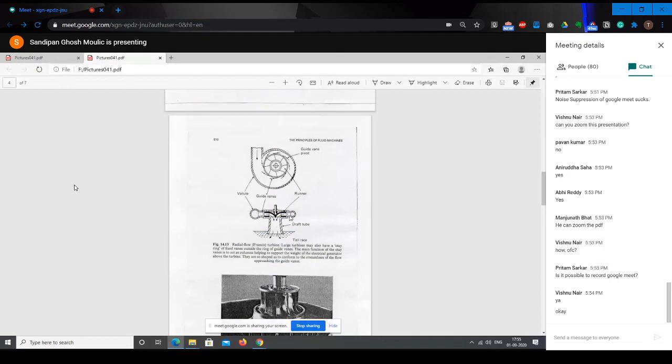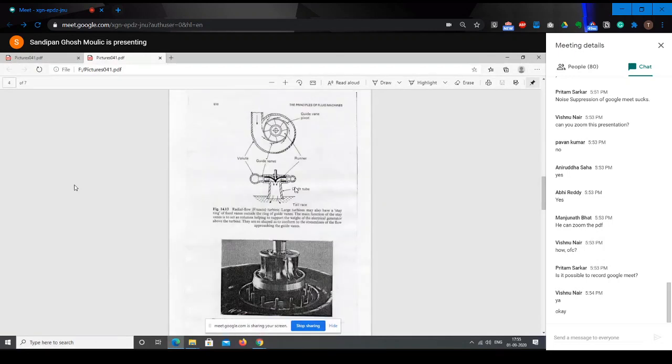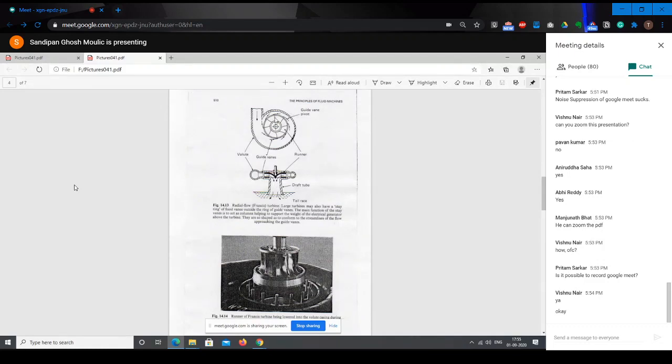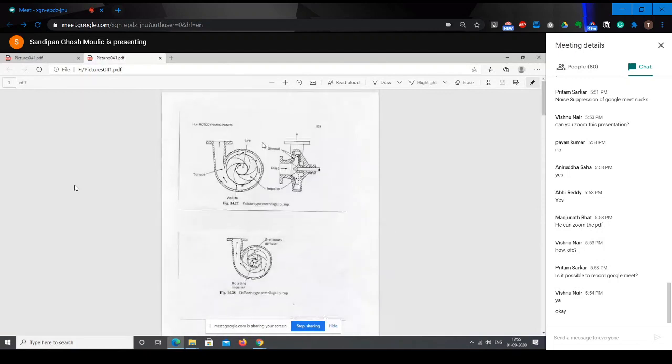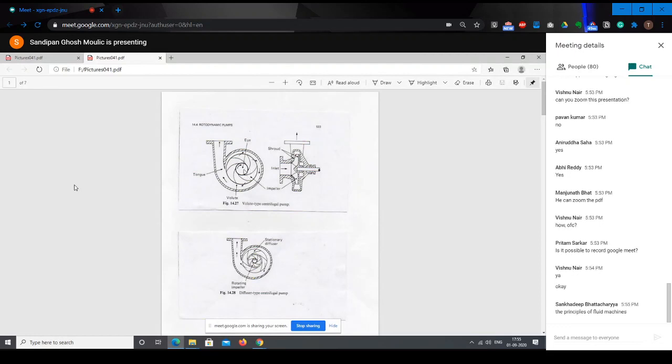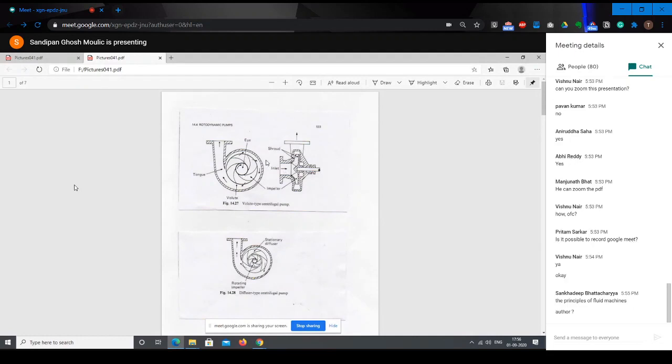Now this figure shows a Francis turbine. So the principle is similar to that of the centrifugal pump, but as I said, in the pump, the fluid enters axially. That is, in this view, top view, here, top figure, it will enter in the direction perpendicular to the screen, turn here and then move out radially. So the motion is from a smaller radius to an outer radius.